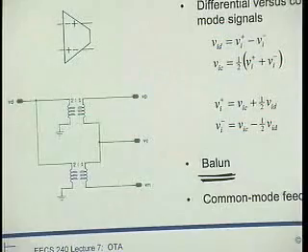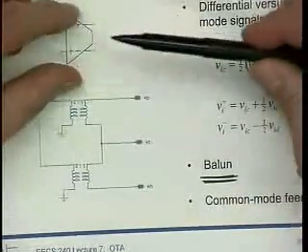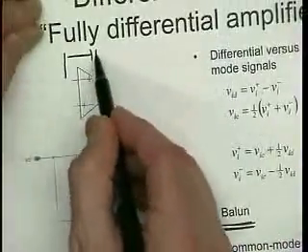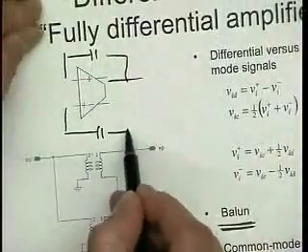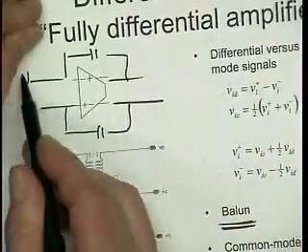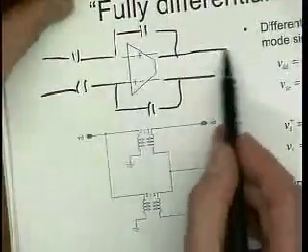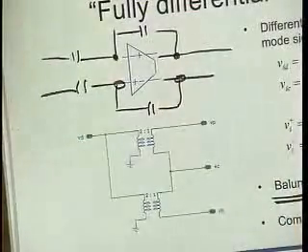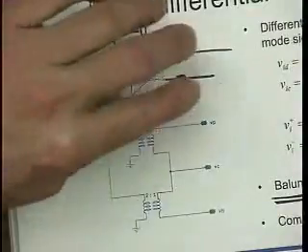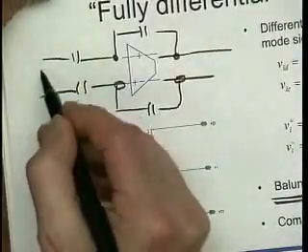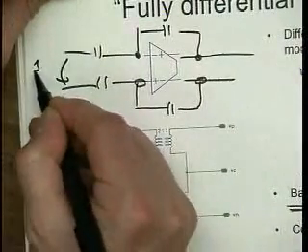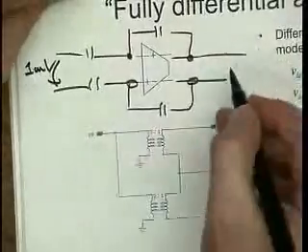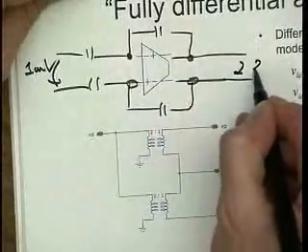But what's the problem? Well, the problem is that in an amplifier like this, when we put feedback around it, this feedback sets only the differential mode. Of course, we could have, let's say here, a 1 millivolt input, and the ratio of these capacitors is fixed such that the output is going to be 2 millivolts.